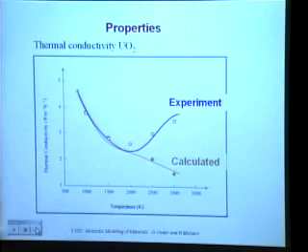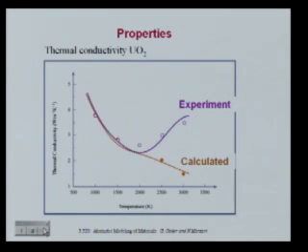And I'll tell you how they calculate this. They calculate this literally by doing a molecular dynamics simulation, looking at essentially energy transport through phonons. And the way you have thermal resistance is caused by phonon scattering. You have a phonon going through, and at some point that wave packet needs to become decoherent, get scattered so it can deliver its energy. But essentially, at least some form of heat conduction comes from phonon transport. And that's what the brown curve is.